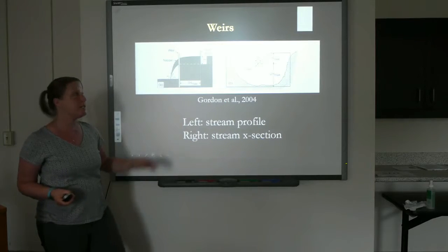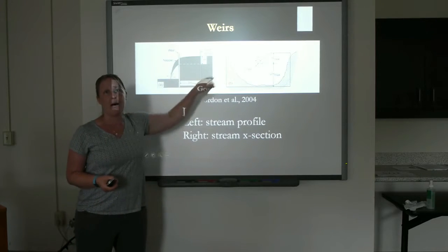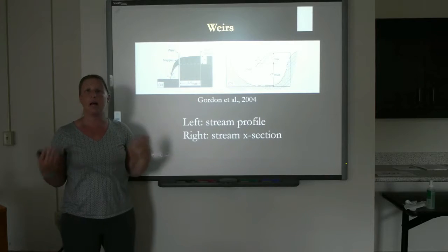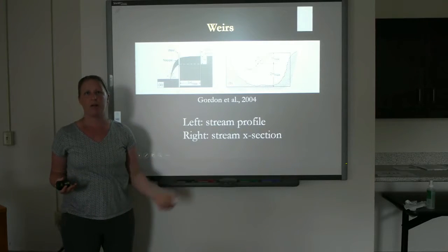One of the limitations is that you can have sediment buildup behind here, and in a site that has a lot of sediment, you may have to clean out behind that weir very, very frequently.